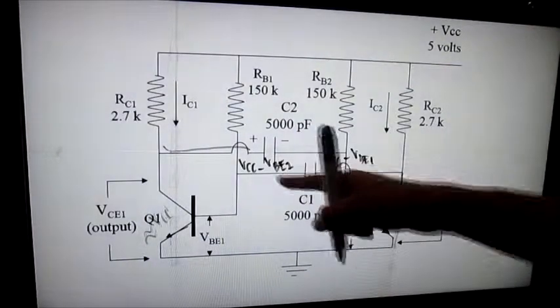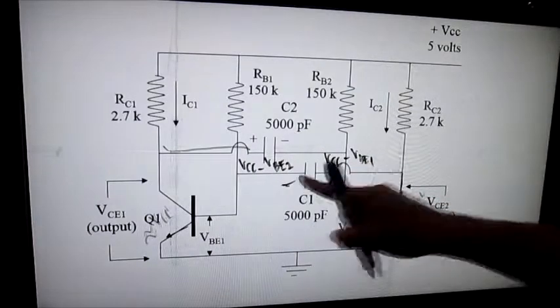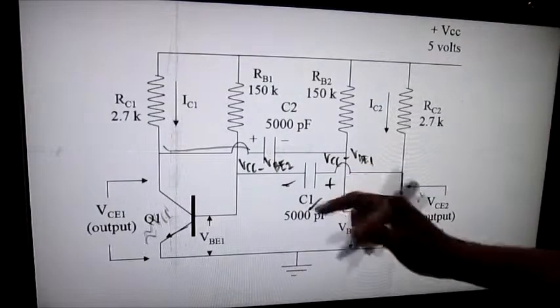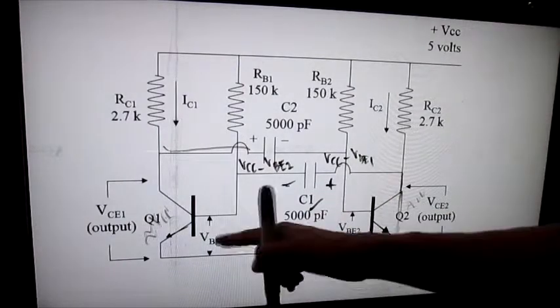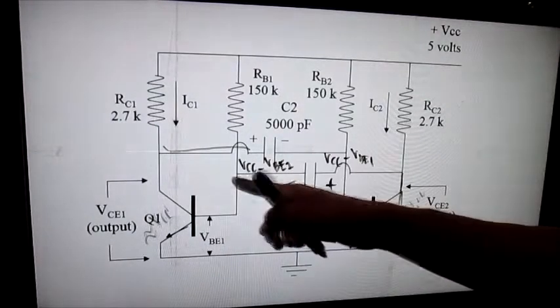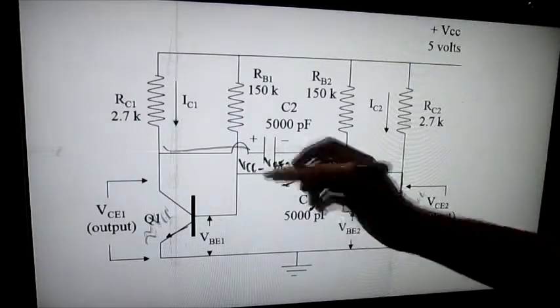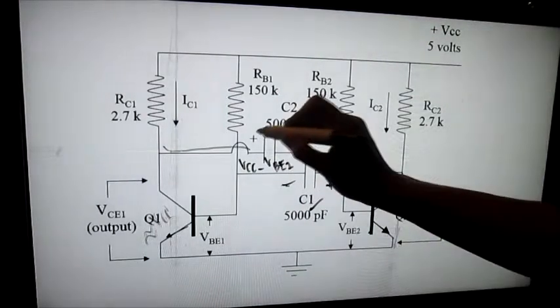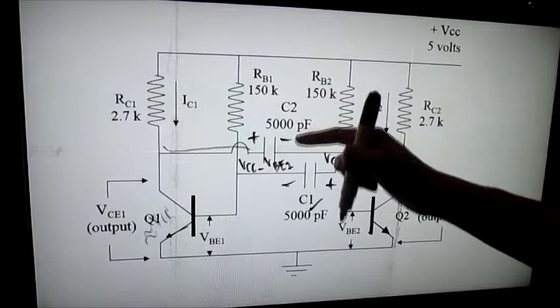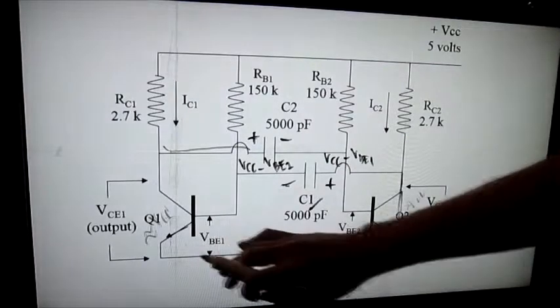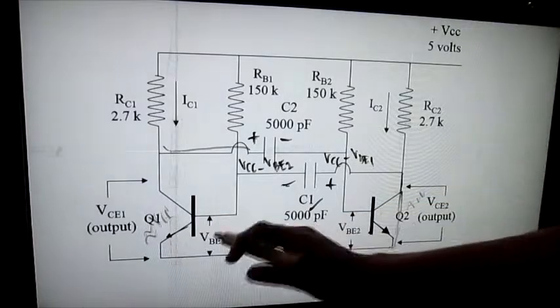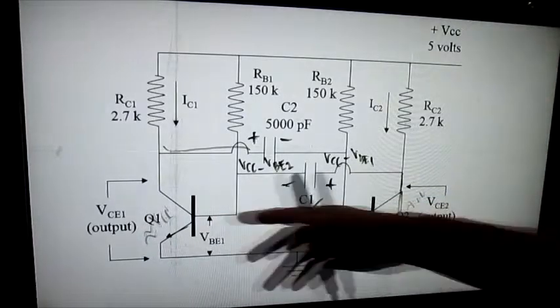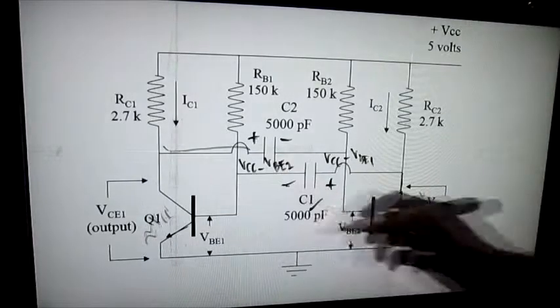After the capacitor C1 has been discharged to around 0 volts, the capacitor C2 is charged with VCC minus VBE2, positive on the left and negative on the right. The base emitter voltage of Q1 is now rising, since its voltage is also determined by C1.